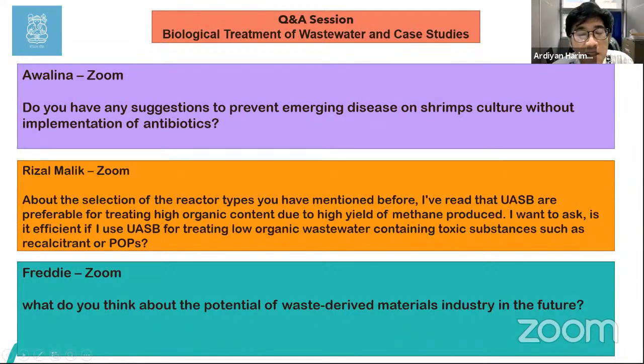Maybe some additional question. Besides the C/N ratio for the toxic substance in wastewater, what other parameters do we need to pay attention to, Prof? If the wastewater has a lot of carbon in the system, most of the time it's the carbon to nitrogen and carbon to phosphorus ratio you need to monitor. In rare cases, you need to add some trace elements. Sometimes they lack iron, because bacteria need a little bit of those trace elements for proper enzymatic activity. So people add some iron to supplement these trace element requirements.